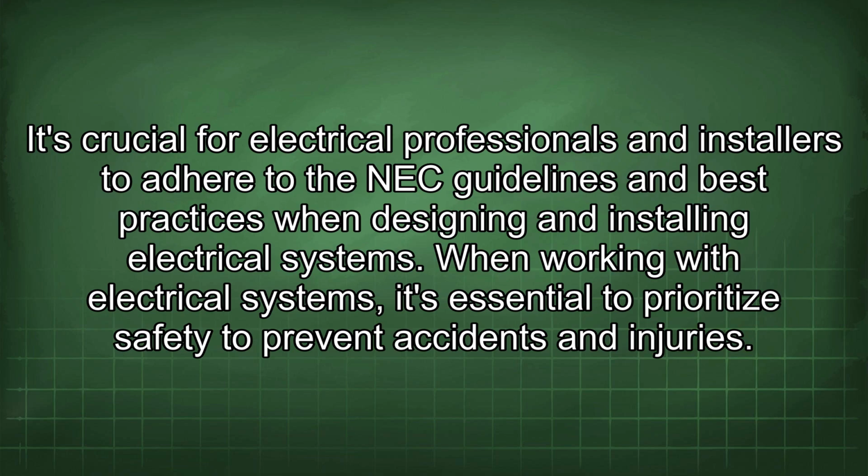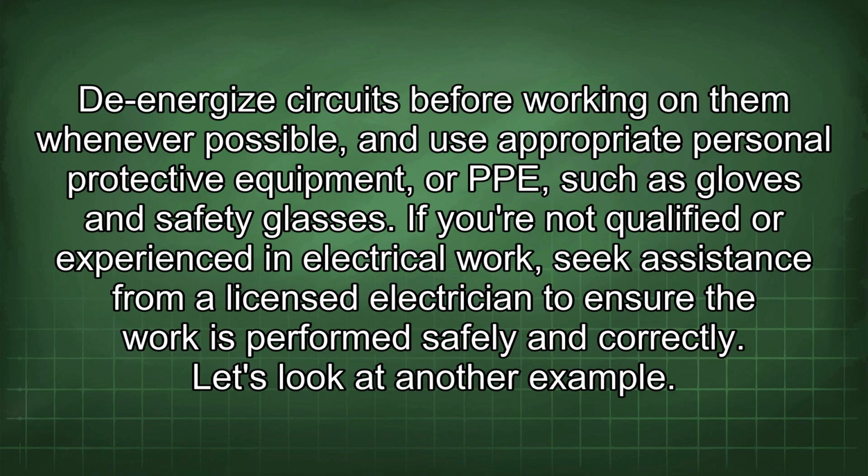electrical systems. When working with electrical systems, it's essential to prioritize safety to prevent accidents and injuries. De-energize circuits before working on them whenever possible, and use appropriate personal protective equipment, or PPE, such as gloves and safety glasses. If you are not qualified or experienced in electrical work, seek assistance from a licensed electrician to ensure the work is performed safely and correctly.